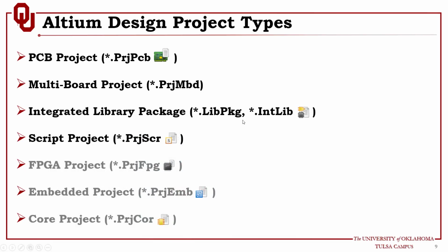Integrated library package. Also, when we create a library, we'll have something called a library package that packages the schematic symbol library and the footprint libraries as well into one library package, where you link the schematic symbol to the associated footprint or multiple footprints.